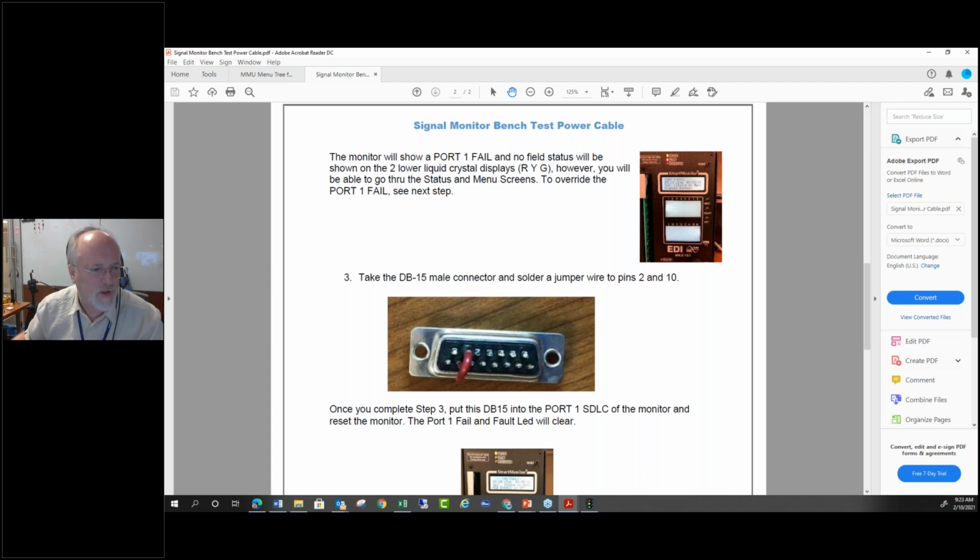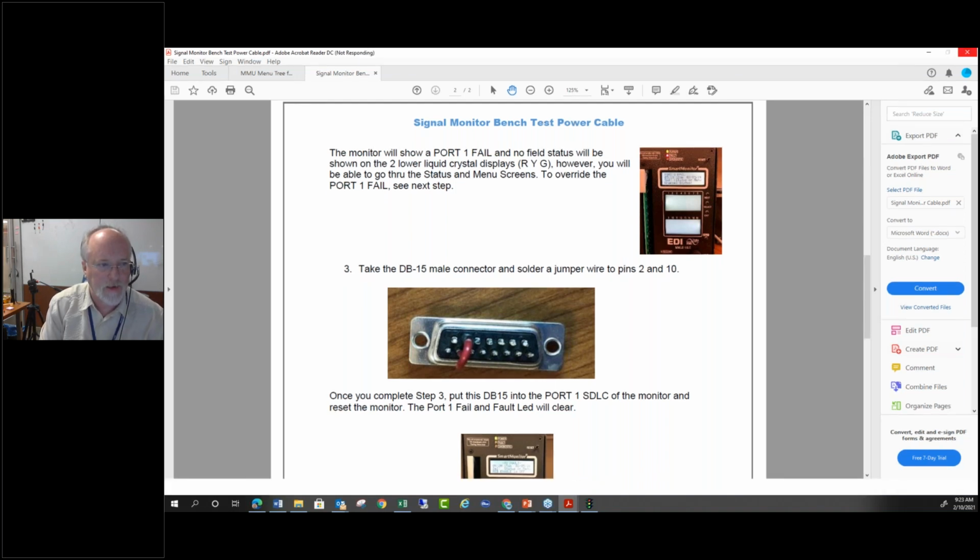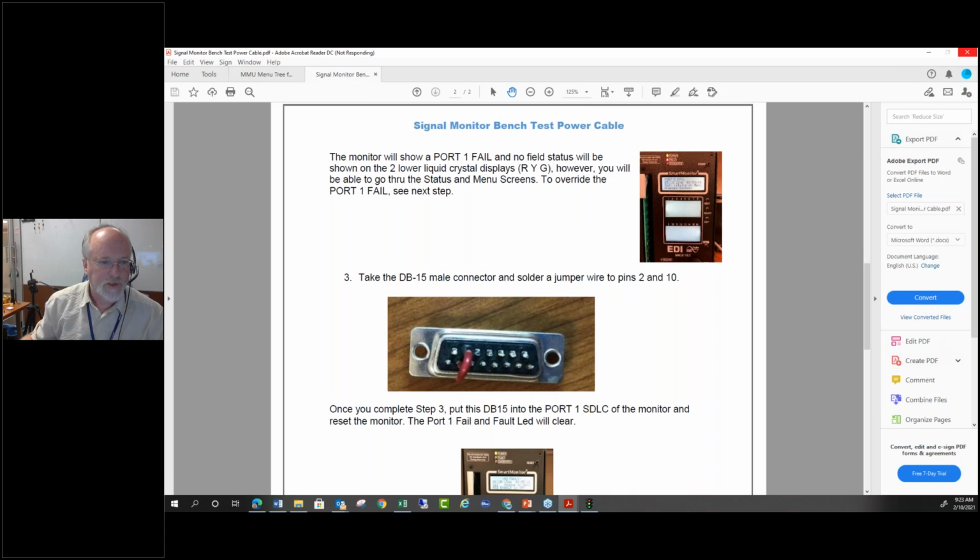I think I talked to Pete about this too. There's the pin HH. If it's on logic ground, it thinks it's in a TS2 cabinet. If the HH is floating or not connected, it thinks it's in a TS1. So what I've been recommending is that you put a switch, like on mine. I don't know if you guys can see